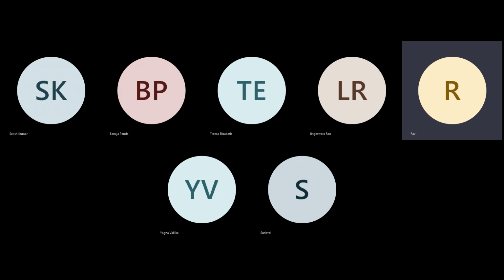It is actually in parts. If you have looked at a log file, there are 20 steps, 30 steps: placement, global placement, step one, step two. The way it is doing is it is breaking down this 1 by 2, 1 by 2. Then it will go horizontal first, vertical next, horizontal next, again vertical. So the 1 by 2 boxes will be broken into 4 boxes, then 4 becomes 8 boxes, 8 becomes 16 boxes, like that until you get into the global box.